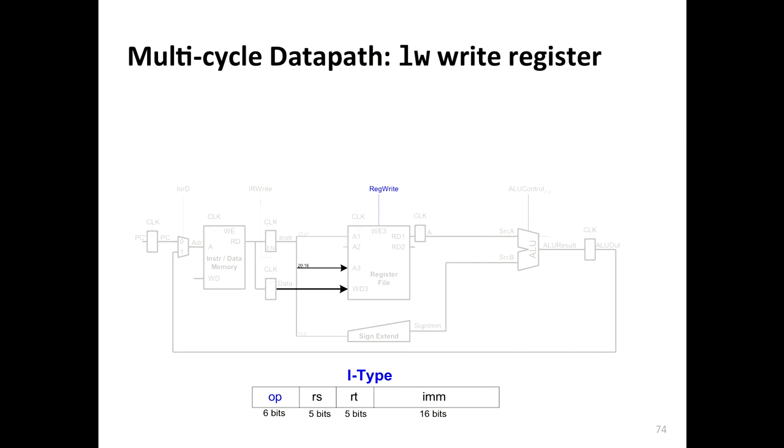And then the last phase in this instruction processing for load is basically you get the data, and you write it to the destination register specified by bits 16 through 20 of what we've stored in this instruction register. So we make use of those intermediate things that we've stored in previous parts of the instruction processing cycle, right? Does that make sense? Is that clear? Okay.